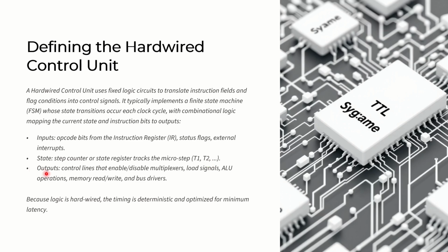Now we'll go to outputs. Control lines that enable or disable multiplexers, load signals, ALU operations, memory read or write, and bus drivers. Because the logic is hardwired, the timing is deterministic and optimized for minimal latency. Now moving to the next page.